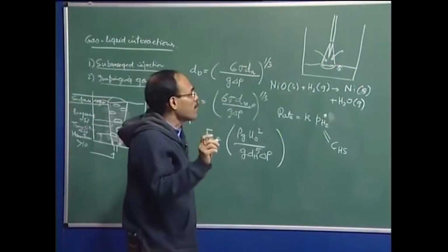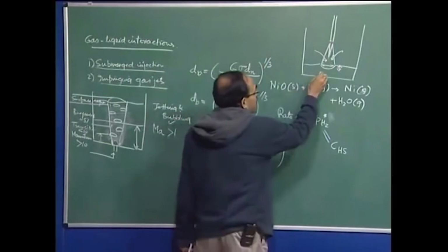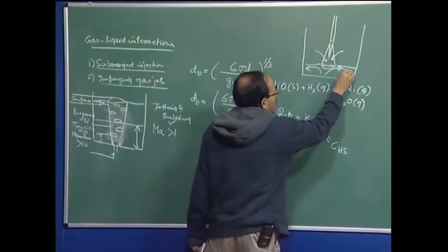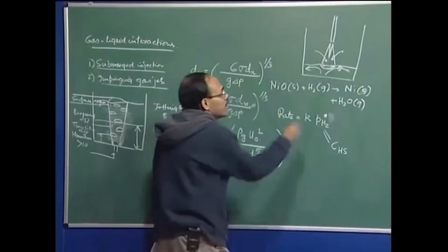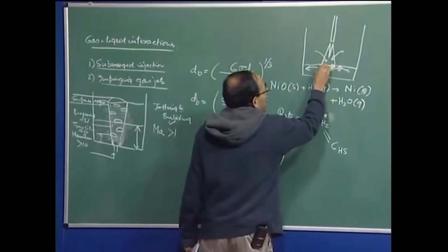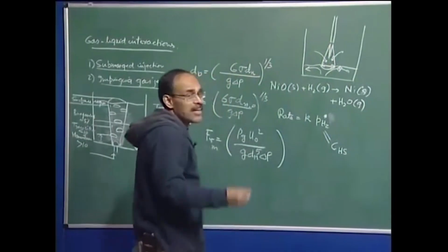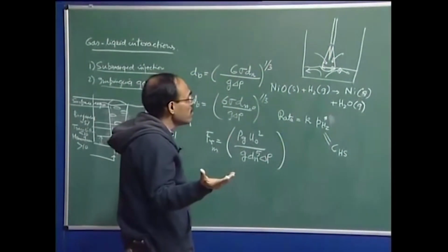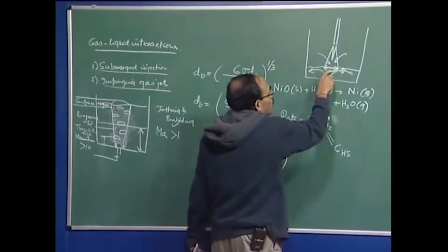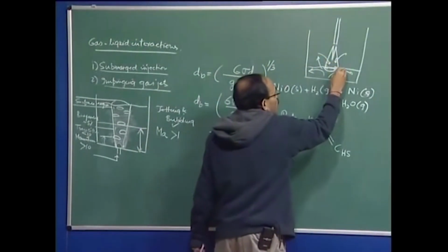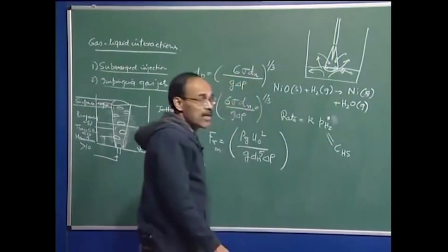The two important parameters which determine the extent of stirring and the dynamics of the system are the cavity depth and the cavity diameter, and these are characteristics of the gas injection. There are empirical correlations available. You may have a very hard blow, and in that hard blow you should be able to drive out a lot of molten metal in the form of droplets and so on.